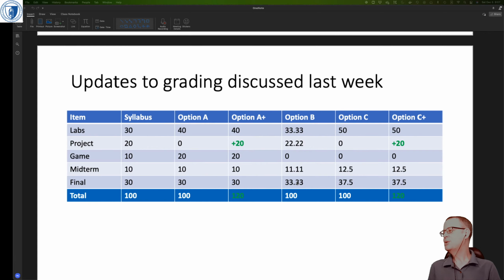Could I briefly talk about what the test bench for Lab 8 should include? The main thing is to just check that the ball counter goes up to 3 and then resets, and the strike counter goes up to 2 and resets, and that each reset resets the other counter.